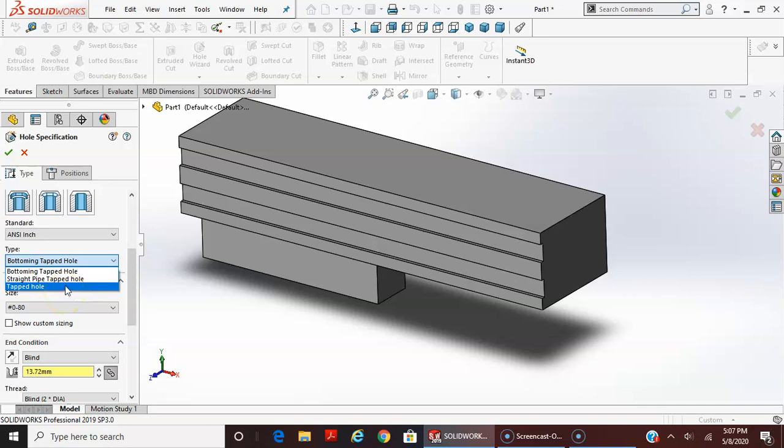And then the straight, it says a straight pipe tap tool, but I'm not sure what this is. I think this might be a specific thread call out that's a little bit different, but I'm not sure, because most pipe thread is tapered, and it actually is the same 60-degree thread angle as both of these, so I'm not sure exactly what this is.